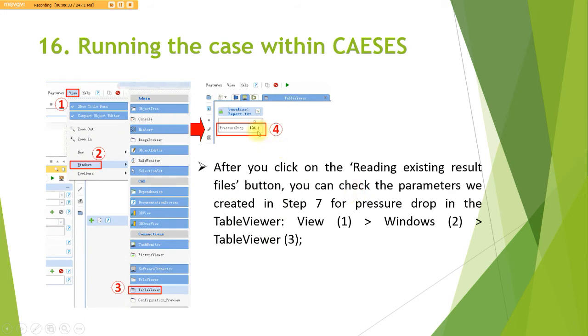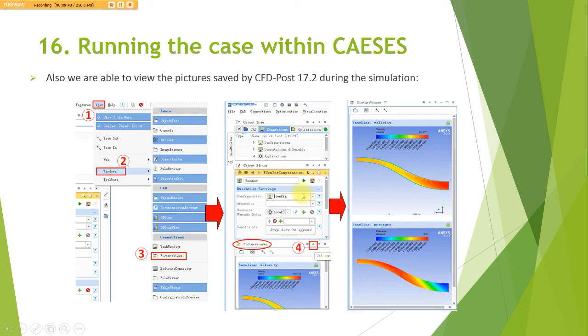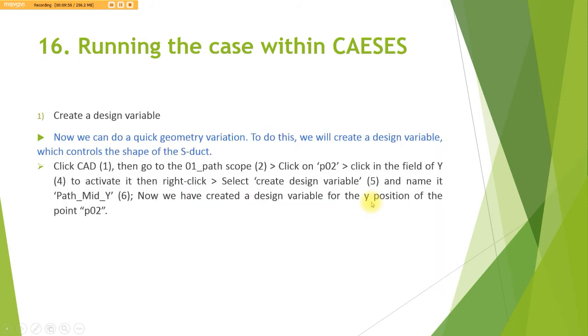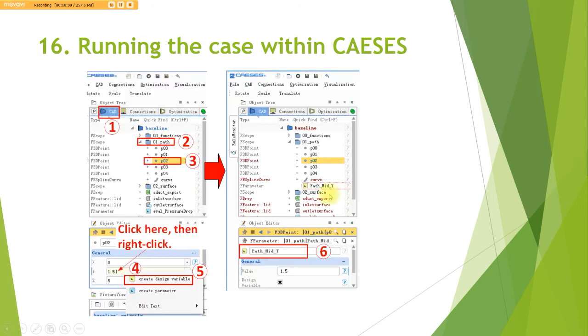If you click results, the new pressure and velocity profile will be shown. And by the way, the pressure you can see is what you set at the beginning, remember. The other thing you could do, if you have parameterized any of these values, either velocity or pressure, any of the inlet conditions or the size, is see all the results for the various cases as well. Just to show you an example, the path of the profile has been parameterized.